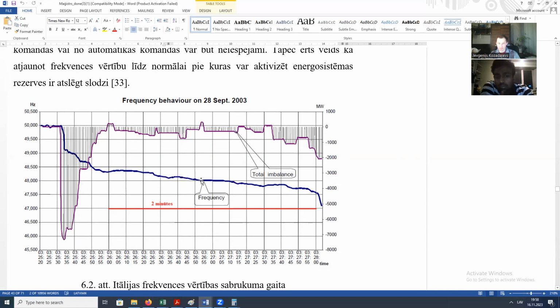drop continues. By the way, we had more sets for the under frequency automation and more groups of consumers that we could disconnect. And all this time, when we lose generators, we continue to disconnect consumers to keep the system in balance. But this is very dangerous. We are in deficit and we are still losing generators. And as we know, the number of consumers that are connected to the frequency automation is limited, approximately up to 50% of total consumption.